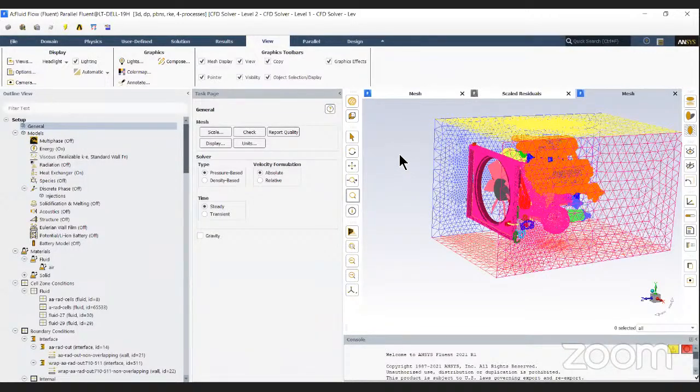Keep in mind, though, in the industry, there are a lot of cases wherein you would have to do a transient analysis. For example, a hot shutdown case wherein your machine is shut down abruptly, and then it starts cooling down in a transient fashion. So for all that sort of analysis, transient analysis might be necessary. This one is just simple for analyzing flow. So we're going with a steady state analysis.